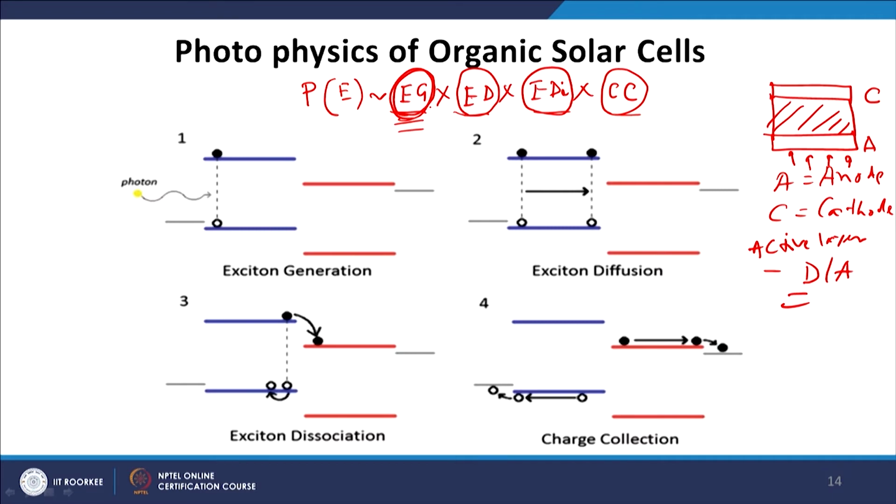Okay. So, now I have a very good low band gap material which can absorb the light and generate a lot of charge carriers, but these charge carriers are now bound. So, to separate them into free charge carriers, what do we need to do next? We need to carry those excitons to the interface of the donor and acceptor. Now, who will carry them? The donor material. So, the donor material has to have very good charge carrier conduction properties.